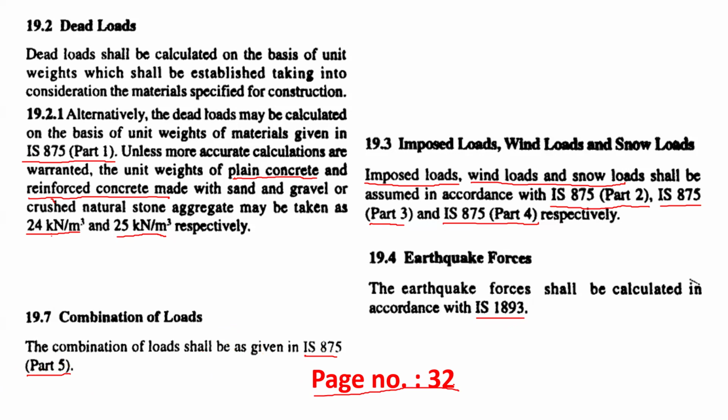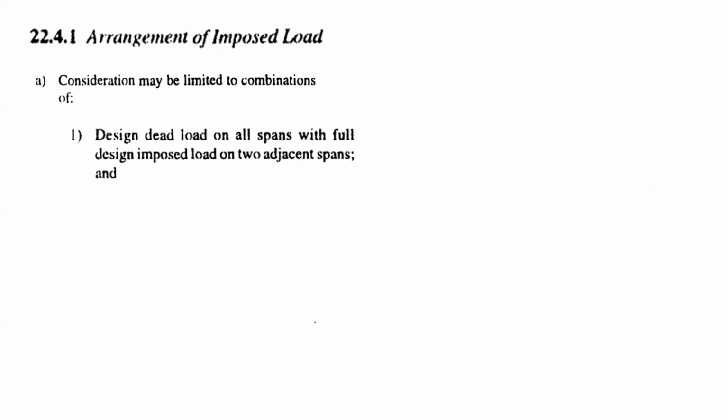In the first few videos, I am going to show only the clauses which are used in IS 456 directly or indirectly. Then arrangement of loads. Consideration may be limited to combination of loads. First is dead load on all spans. Dead load is always there. So keep in mind, dead load on all spans and design imposed load on two adjacent spans.